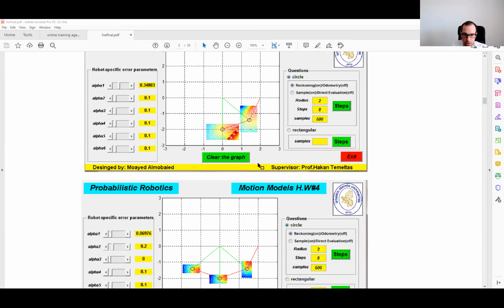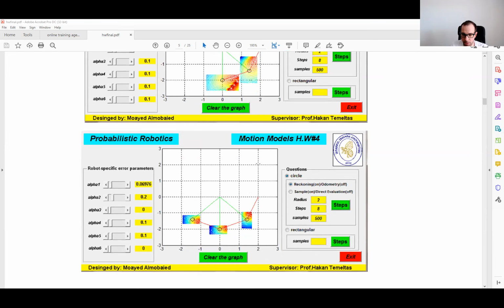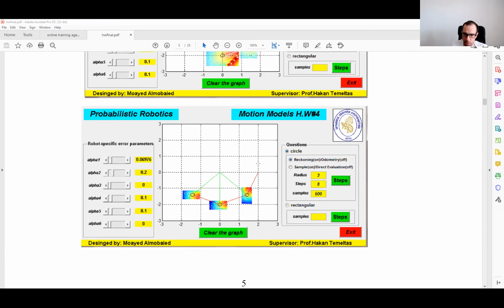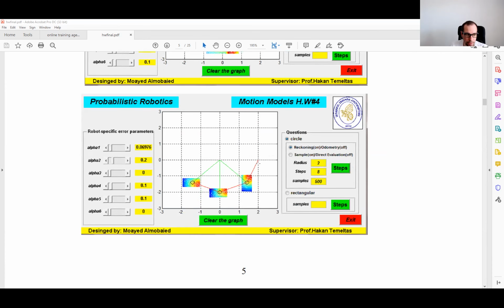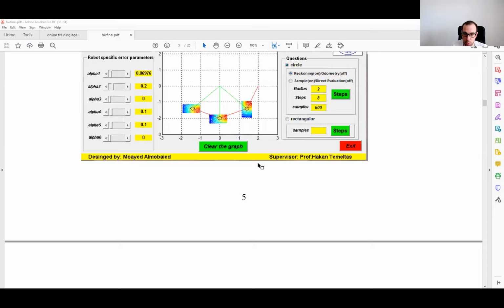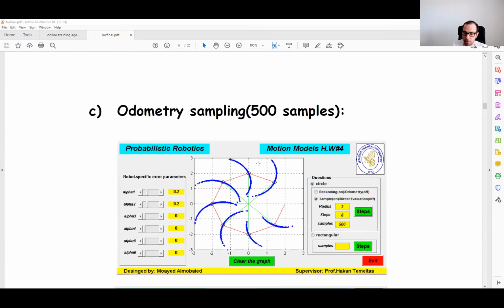Yeah. So ROS, if you look at it from a very bird's eye perspective, is basically a messaging system between any kinds of programs. It defines the protocol for messaging as well as the messages that are typically used in robotics. That's the core of ROS. So you have roscpp, which is the C++ library, and rospy, which is the Python library.